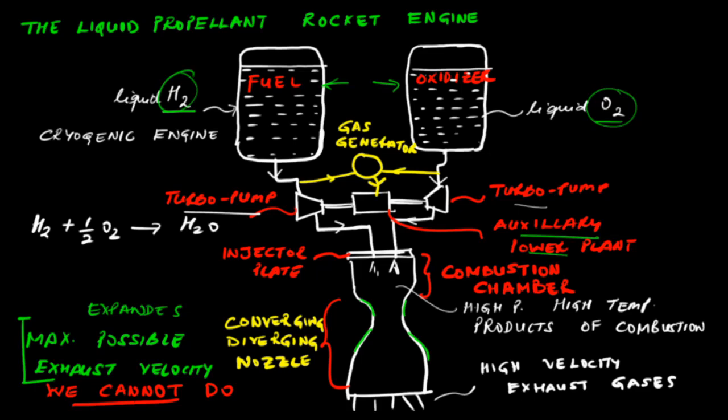Thermodynamics tells you that you cannot achieve an exhaust velocity that is greater than the velocity that you would get from thermodynamic analysis. So someone might say that, okay, that really doesn't help me, but indeed it is really helpful, because let's say you are looking for some fuel and oxidizer so that you want to achieve a certain amount of thrust, and that depends upon the exhaust velocity that you can get. And now if you already know that you cannot exceed this particular velocity, then you need not waste your whole lifetime to achieve that high velocity.